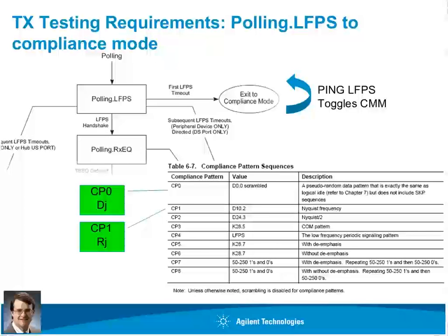For USB 3.0, you don't require external PC-based software to run the test tools and put the device into the proper test modes, which is a big improvement for testability, particularly for mobile or embedded environments that don't support Windows operating system, which the tool requires.